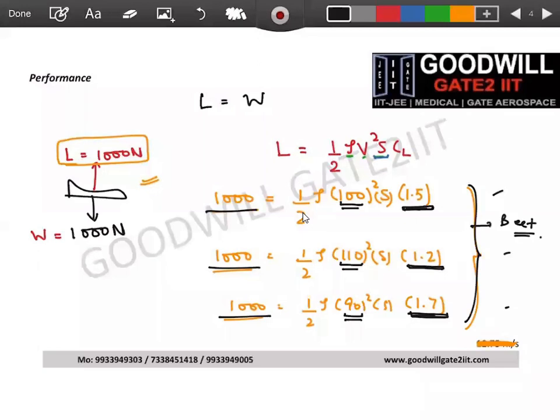If you want to maximize anything, should I fly at any of these conditions or is there one best possibility? No, not at CL max, Siddharth. I'll come to CL max in a bit. Ankan told me minimum drag. Now the question comes: should we really operate at the condition in which you have minimum drag, or should you operate in a condition in which your engine is operating under minimum power, or there is one more condition which is referred to as the minimum D by V condition?